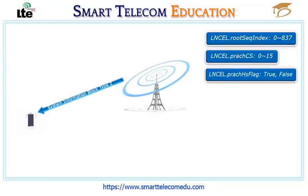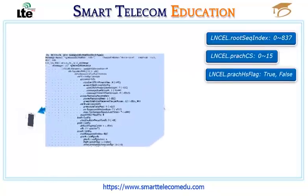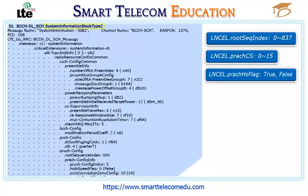The UE receives the parameters to generate the 64 preambles in System Information Block Type 2, in PRACH configuration setting as follow: root sequence index, high-speed flag, and the zero correlation zone config. The setting of PRACH CS parameter